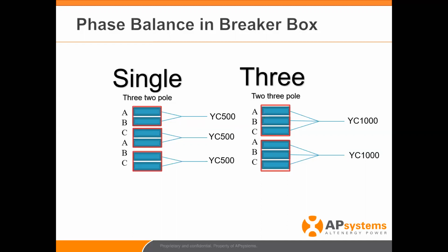If you switch over to single phase, if you go to the YC600, you're looking at a total of 6 inverters for a total of 12 panels or 12 modules. And for the QS1, it's 3 inverters for 12 panels. Which I believe for the 600, I believe it's 7 units for a total of 14. That's only for single phase, but for 3-phase, it's actually 6.